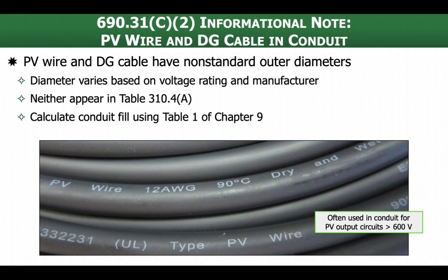Or maybe I'm just running wires off a roof, and sometimes I would transition to a wire and run it in conduit because it would be maybe cheaper and smaller. But in this case, I'm running PV wire all the way down, and it's got to go through conduit to make it there. In that case, we would need to do the same thing. How many can we put in that particular size of conduit? So something to keep in mind when you run into that.